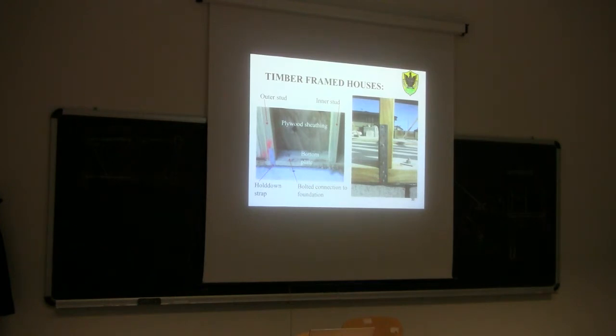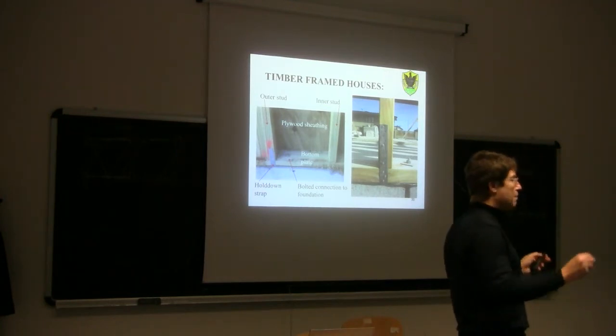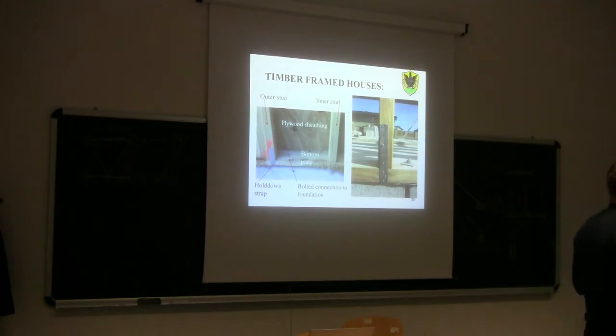Okay? This is because in this kind of structure used in New Zealand, UK, typically the prefabrication involves only the bare frame. So the bare frame is prefabricated outside. Then it is delivered on the building site. We will see now. It is placed vertically with some temporary bracing, and then it is clad with the sheathing. Okay?